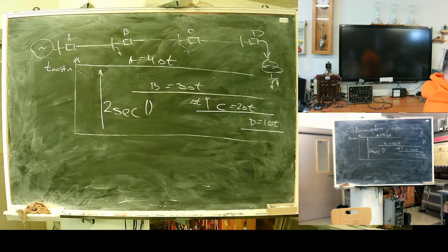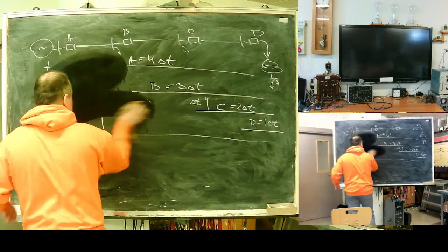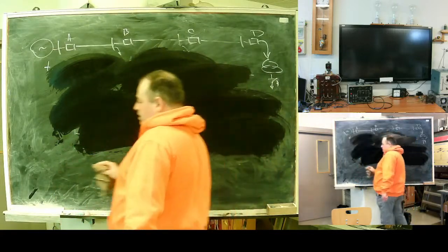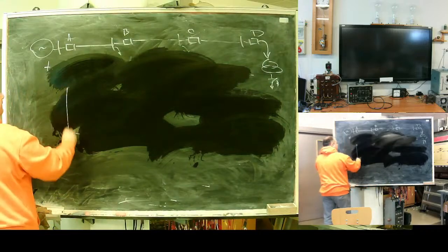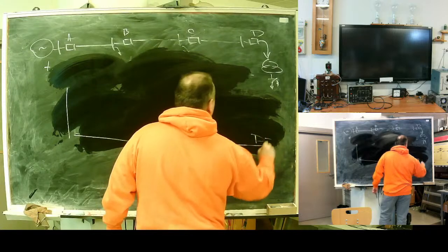What to do? We cannot cut delay time because we need to maintain selectivity. We cannot cut delay time for the whole line. What can we do? Remember my yellow line. So here is D1.